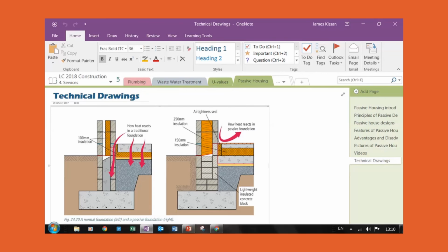And no matter how you build this, if you go with the traditional method, build your wall, then pour your floor on top, your floor will dry out. And when your floor dries out, the concrete dries out, it shrinks a small amount. That means there's a gap between your floor and your wall. And in a traditional house, that's where air will circulate down, and you'll have heat loss down through there.